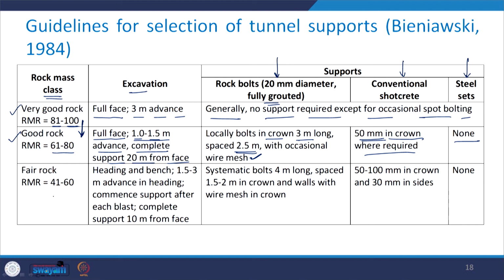In case you have the fair rock where the RMR varies between 41 to 60, one needs to go for the excavation as heading and benching, and one can advance 1.5 to 3 meter in heading, and one should commence the installation of the support system after each blast.